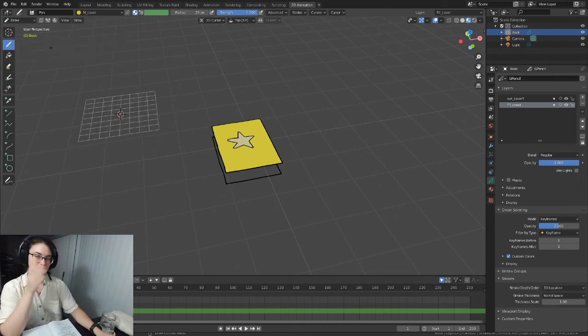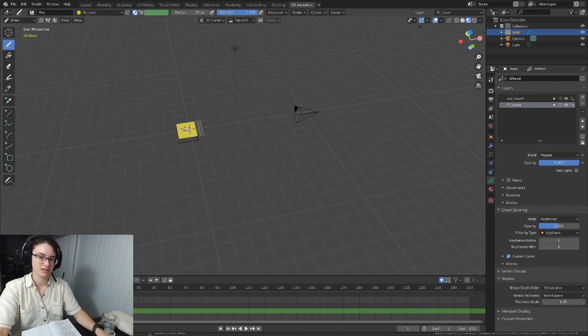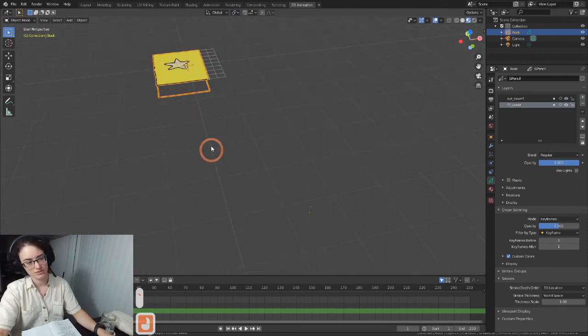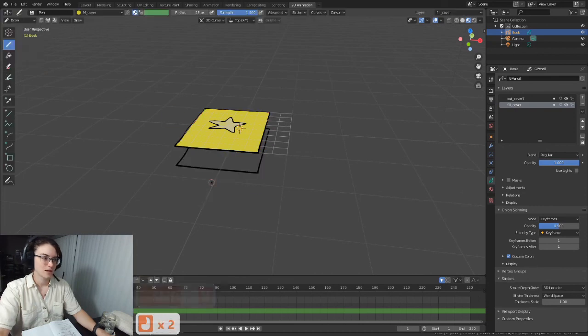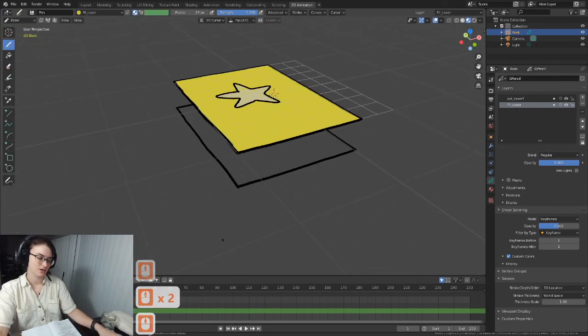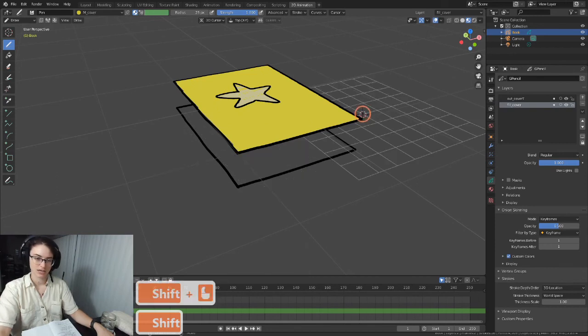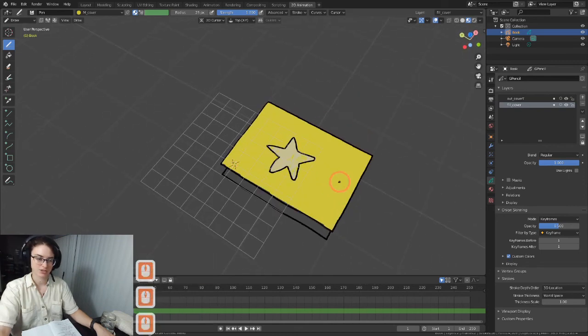If you moved it and you didn't mean to, we can center it by hitting Shift C. It'll reset your screen, so you might then have to do object mode, do your tilde, do view selected to rescale down. But our hotkey for placing our cursor is Shift right click. So anywhere my mouse is, if I hit Shift right click, it's going to pop my cursor there.